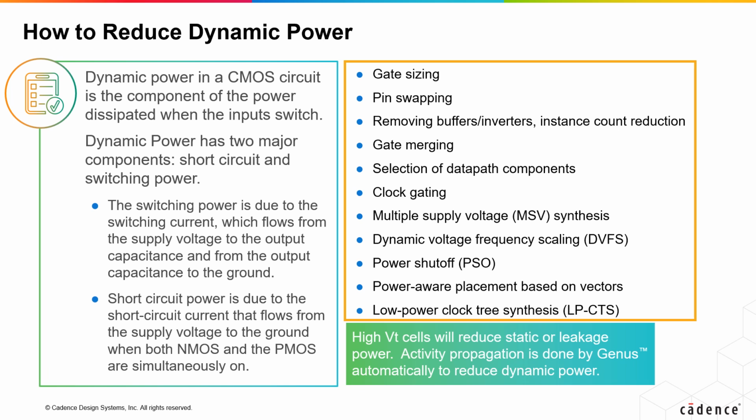If you do not need a higher frequency for certain blocks in your design, you can also reduce the frequency. Power shutoff, PSO, technology lets you turn off power for certain modules using this. Power-aware placement based on vectors and low-power clock tree synthesis, LPCTS. We will be discussing these methods in detail in the subsequent chapters.